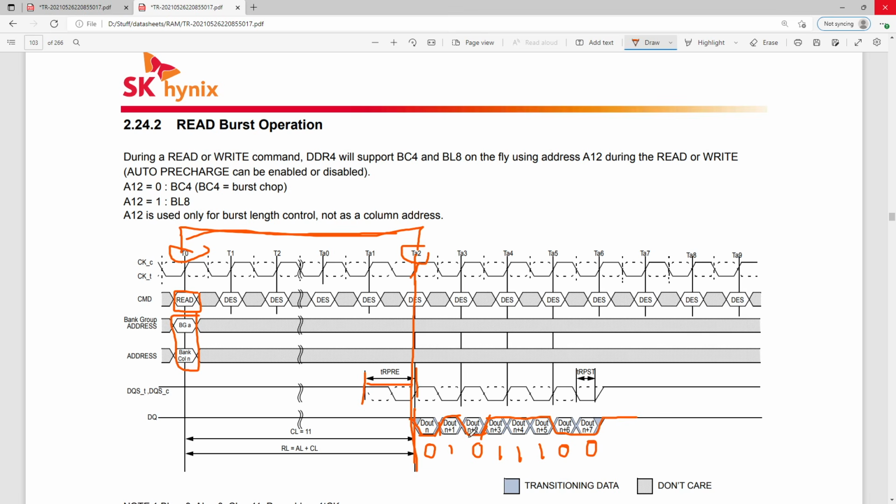So what the memory controller does during a read operation is that internally, and there might be other ways of doing this, but I'm aware of at least one style of DDR controller doing this, the memory controller internally has a second clock signal known as a read clock, which is 90 degrees shifted relative to the actual clock that the memory has. So basically, inside the memory controller, we have a clock that looks like this relative to the main clock, right? It's on a 90-degree shift, so it's out of alignment with the main clock by 90 degrees.